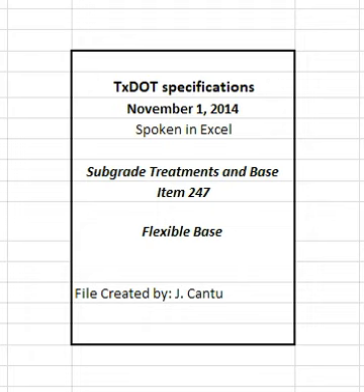2.2 Water. Furnish water free of industrial wastes and other objectionable matter. 2.3 Material sources. Expose the vertical faces of all strata of material proposed for use when non-commercial sources are used. Secure and process the material by successive vertical cuts extending through all exposed strata, when directed. 3. Equipment. Provide machinery, tools, and equipment necessary for proper execution of the work.